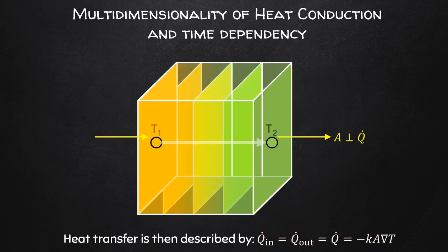So in our analysis, we decide, for example, through which area heat is being transferred, or through which area heat is flowing. The area is always perpendicular to heat flow. So the area that we consider must be perpendicular to the heat flow. Always remember this. Therefore, the area profiles we need to consider in this case are shown by the varying colored squares going from orange to yellow to green. So in other words, the area in question here is y multiplied by z.